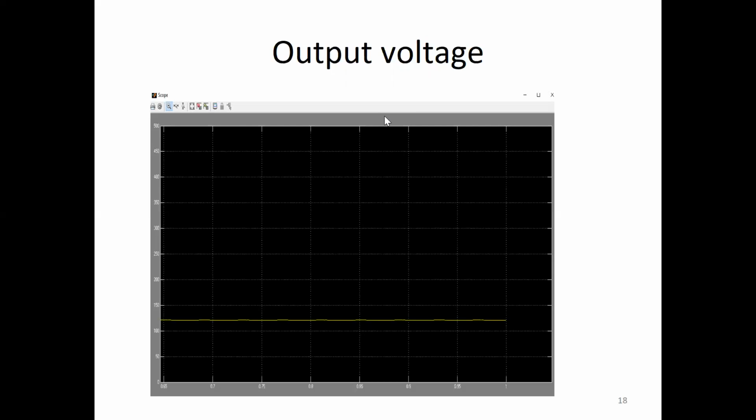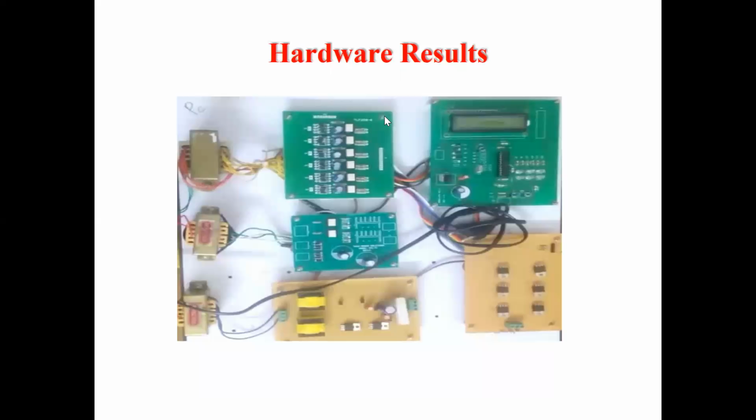And the thing is that there is no limit for the conversion. It depends upon the application; according to the application we can decide the output voltage. Even if you want 10 volts, we can get 10 volts, or if you want 200 volts, we can get 200 volts. That all depends upon the values that we use in the circuit, whether all the LC values determine the output voltage levels and the current levels.